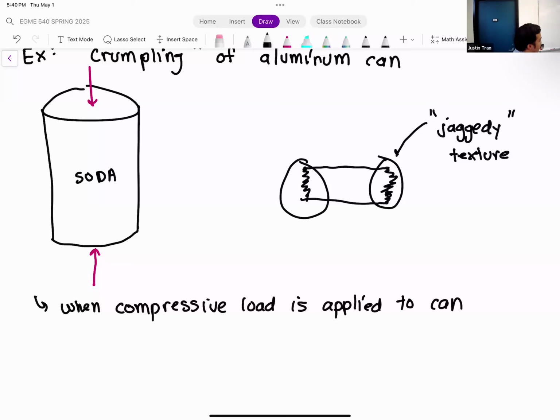On the surface, you may think that we applied enough compressive force to achieve material failure in the can, okay? That can happen, it is possible to apply enough force for that. But likely what's happening first is that you're causing buckling of the aluminum structure before you get to material failure.